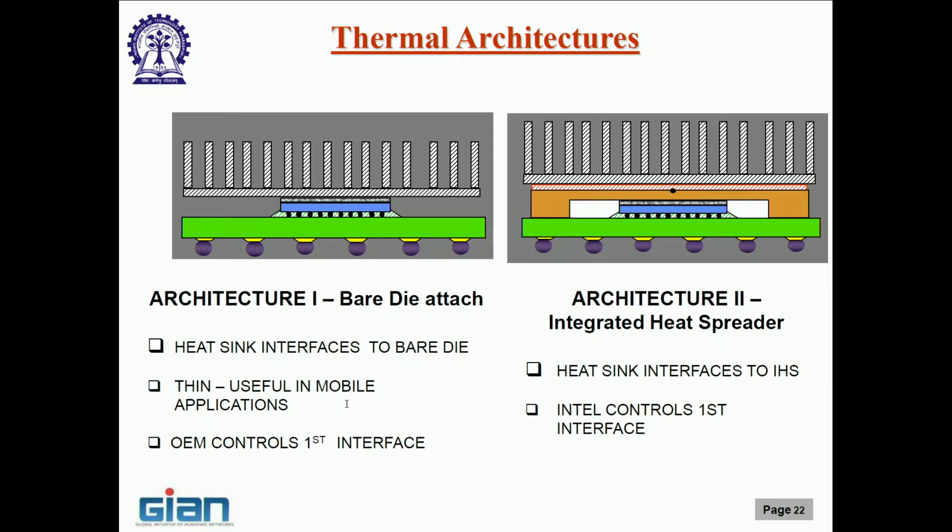Now, what happens is a company like Intel or AMD who makes these processors is going to sell the package with the bare die to the OEM, which is the Dells and HPs of the world. Okay. Dell, HP, Toshiba, whoever makes the final computer, the system. And then it is these companies, Dell and HP or Lenovo, who are going to attach the thermal solution and control what thermal interface material goes in and so on.